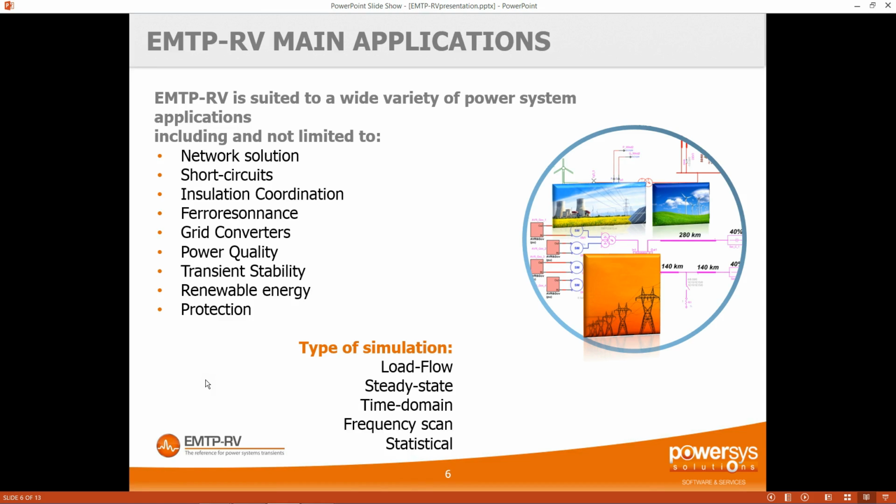But instead of going to the Laplace world, the transient software will integrate this equation step by step, because one of the assumptions in Laplace is that the model is valid only for the fundamental frequency, whereas for a transient software you don't make any assumption. Of course, the time steps have to be smaller than in the frequency domain.